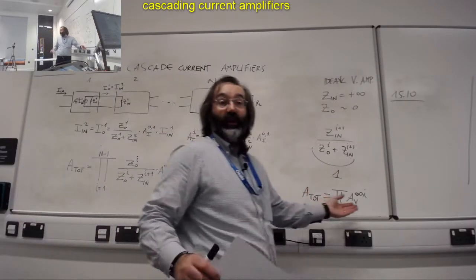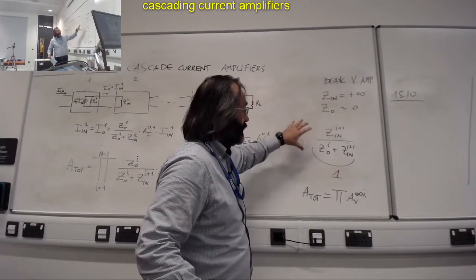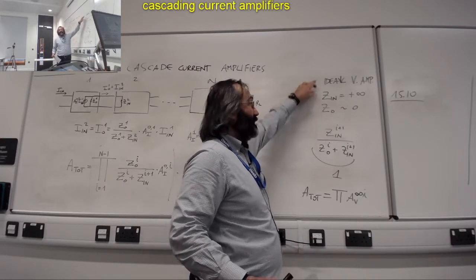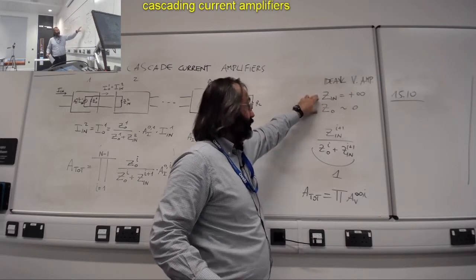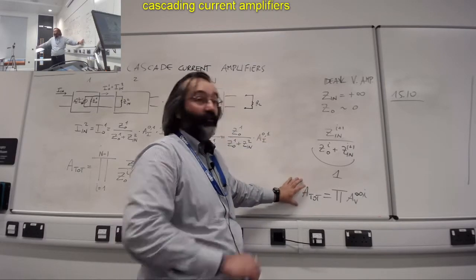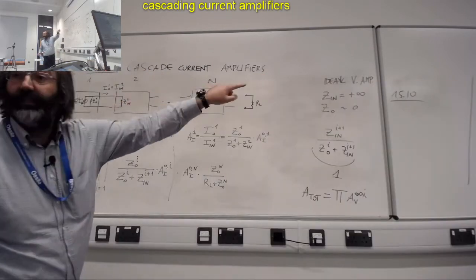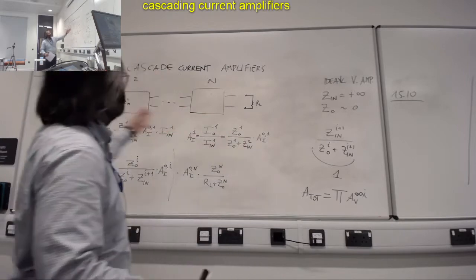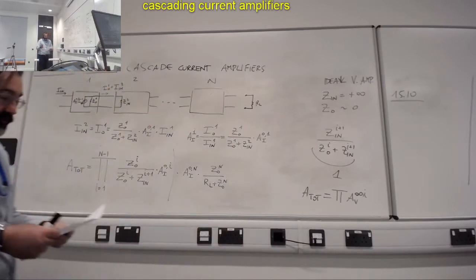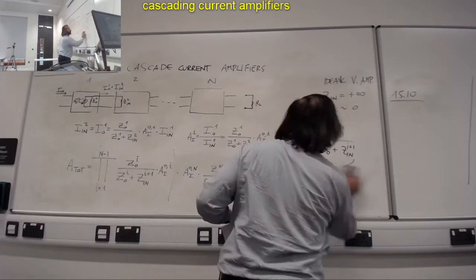I don't know if you, unfortunately, I should have done it previously when I had the formula here. Okay, but the point is, if you are in this situation, which basically means that it's an ideal amplifier, then these terms become 1. And so the total amplification of the cascade is indeed the product of the amplification of each stage. If not, the total amplification is smaller, as we discussed previously, because there are also these terms to take into account. And probably I can repeat this concept here.